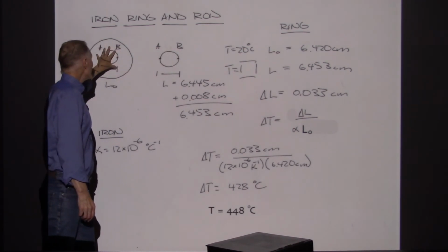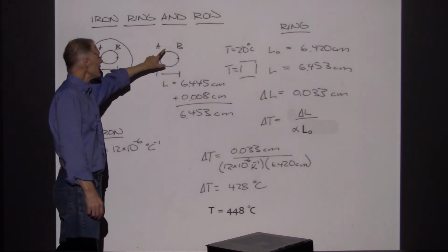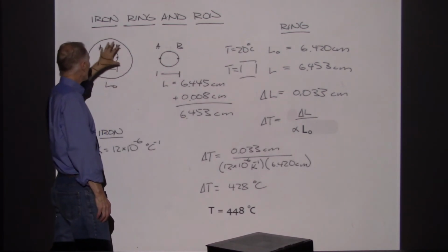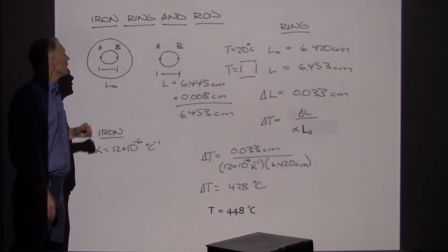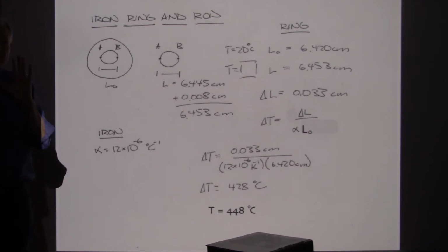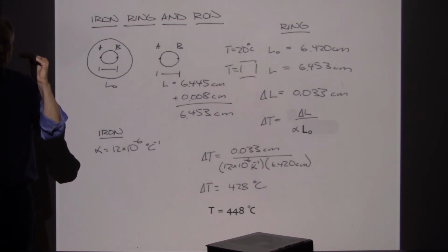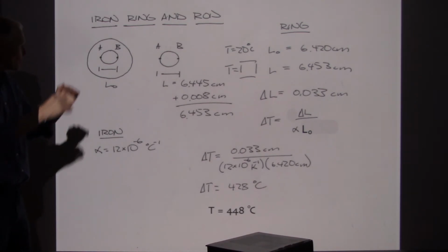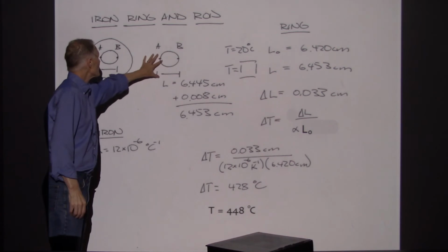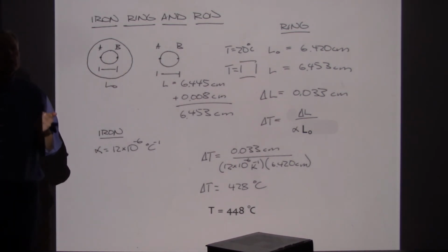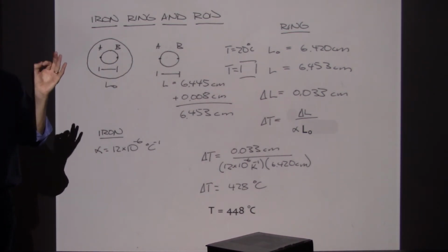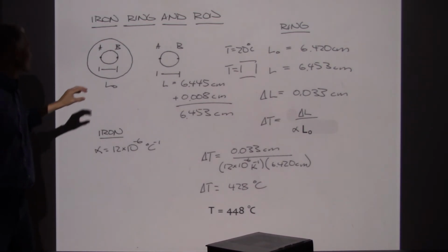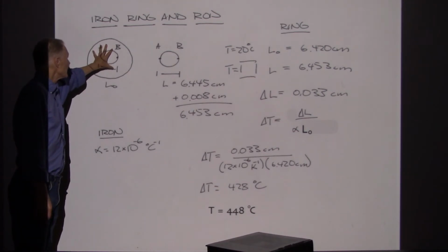Now, it doesn't fit, but what you can do is either contract this, bring it down to a really low temperature, or expand this, either one. So that temporarily at least, because of the temperature differences, the rivet will fit inside. Then when the temperature comes back so that they're both at the same temperature, you've got a really tight fit. You've got a piece of metal rivet in there that's too big to be there, and so this really clamps down tightly on the structure.